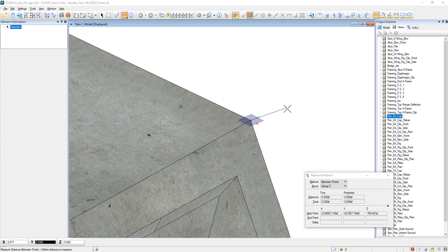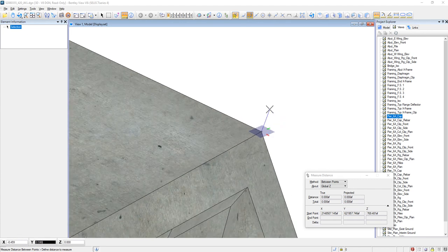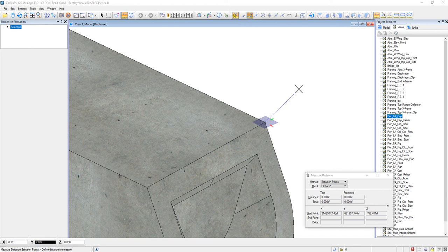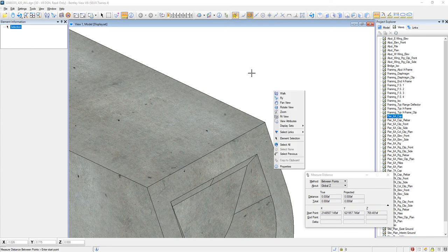So in order to change the direction or orientation of this, we can hit the R button. And if we hit the R button, you can see down here in the lower left, we have a little toolbox that shows up. And it's showing all of them that are associated with R. So RE, if we typed in RE, it's going to rotate that ACS about an element that you select. So let's go ahead and do that.